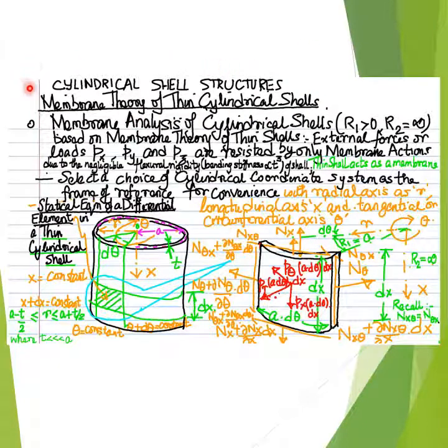As a result, the out of plane bending moments Mx, My and out of plane torsional moments Tx and Ty in a thin shell are themselves negligible or have to vanish by virtue of the thin shell assumption, because of which the thin shell is unable to resist any out of plane bending moments or torsional moments.